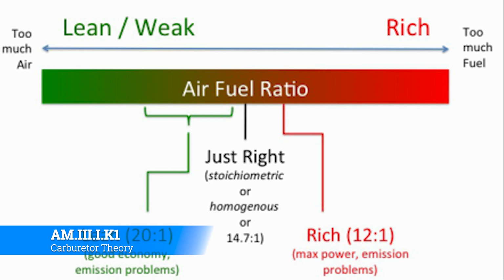One of the reasons a cold engine will start and sputter is because it's so cold that it really disrupts the atomization of that fuel and causes it to kind of glob together and not really want to spray appropriately. You end up having a poor atomization pattern, so therefore it doesn't want to fire off as efficiently as possible.